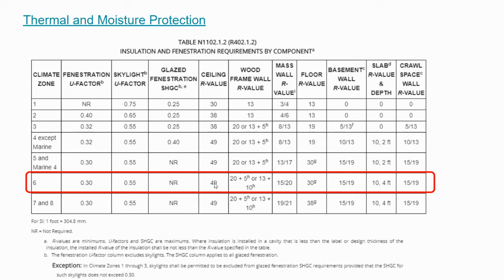So if I have 2 stories, the ceiling between my first floor and second floor does not need an R value 49, because that's inside our envelope of insulation. But the ceiling above that floor, if I only have 2 floors, on the ceiling between the second floor and the attic, that needs to be an R 49.